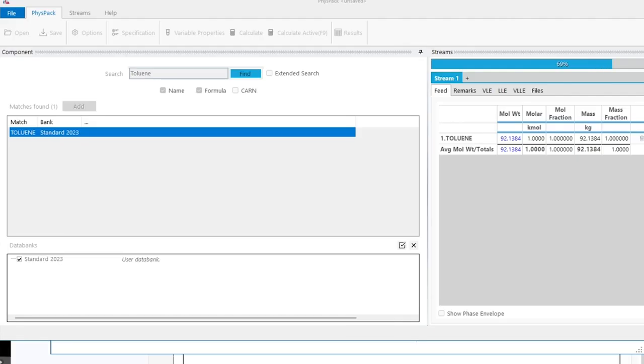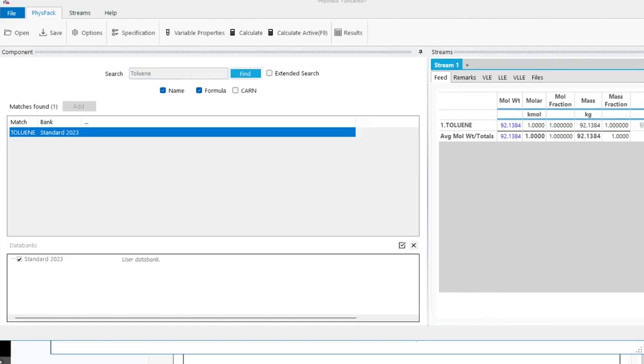It will do an integral, and we'll see this in a minute when we look at the data, throw it into an equation, and what it will basically do is draw a nice pretty graph, and we'll find a peak, a maximum mass flux. And that's what we're going for, mass flux from our face. It'll tell us our maximum mass flux, and that's the number we need. That's the number we can use for our device sizing. That's where we're getting choking.